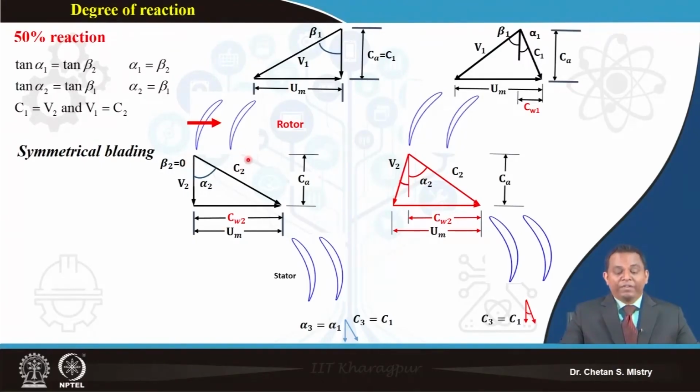I will have this absolute velocity component large, and that will be passing through this stator passage, giving diffusion. So according to what we have learned, for a degree of reaction of 50%, maybe you can make your velocity triangle accordingly. Just look carefully at what inlet condition is given, whether you have axial entry or it is at a certain angle.